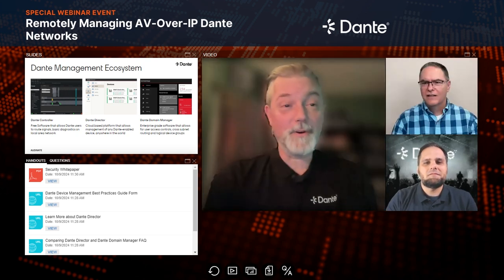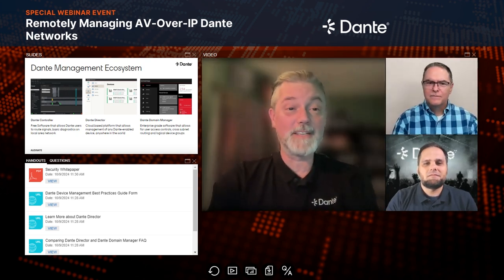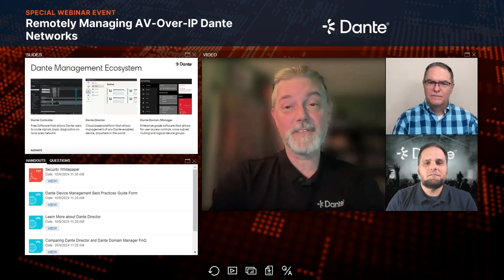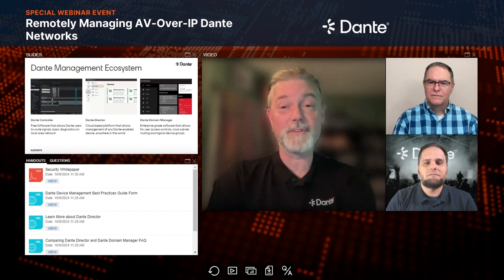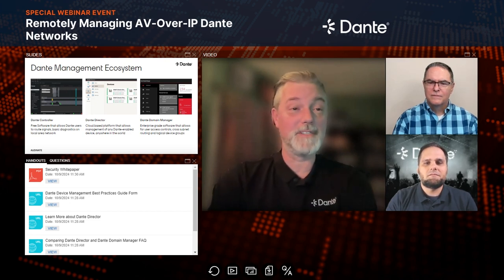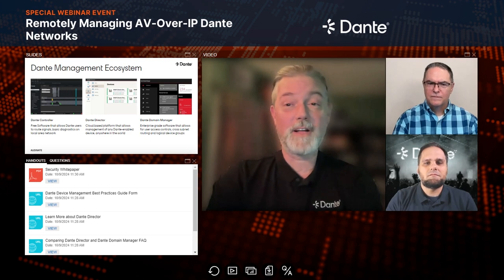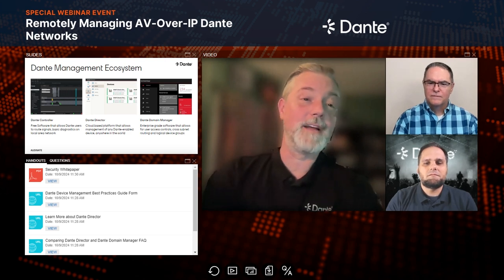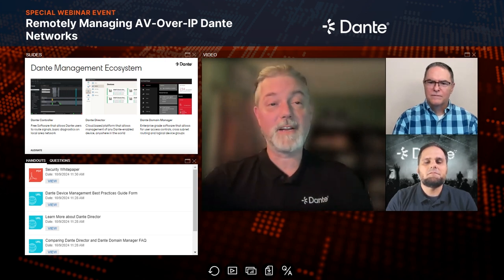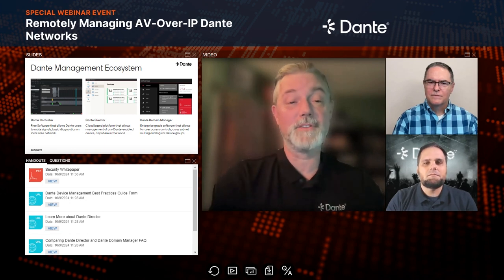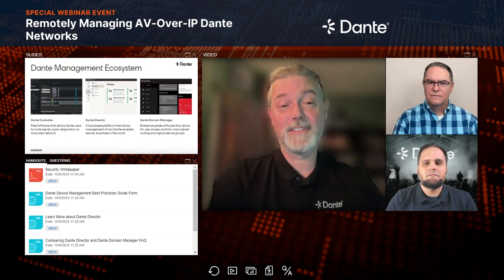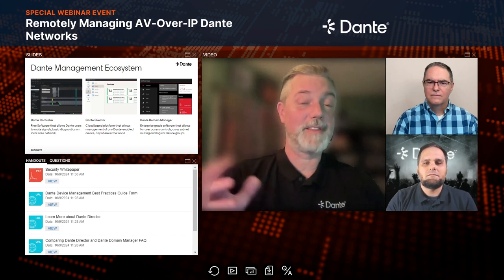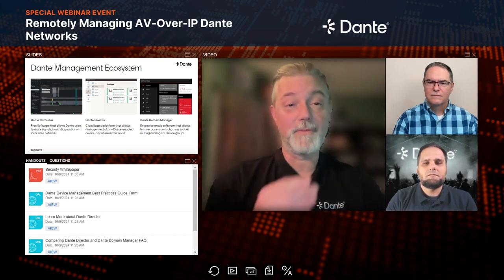Well, Dante Controller is something that everybody can get. So Dante Controller allows just basic signal routing and so forth. There's some diagnosis and configuration tools that are directly within Dante Controller that are going to be beneficial to pretty much anybody. So you can set your clock, set your timing, set your sample rate. You can set a lot of different things directly using Dante Controller. Dante Director is a SaaS service that allows you to manage everything and even change a lot of your signal routing and so forth, but also do